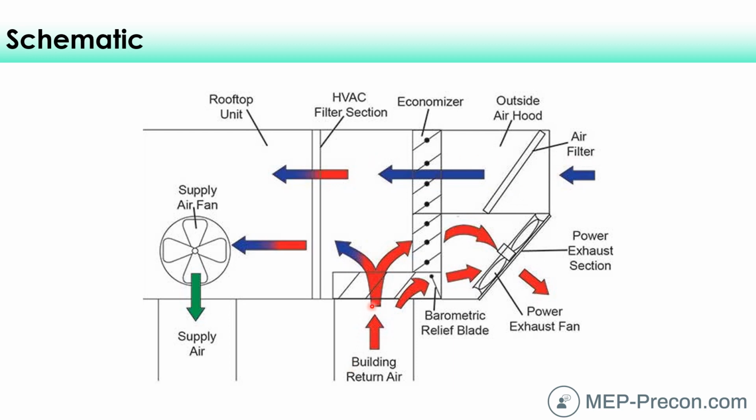It relieves just by the geometry of how it's made. It's meant to come through here, and it just gets relieved through normally just a barometric type system. There's a barometric damper, which means it opens up just based on the pressure behind it.